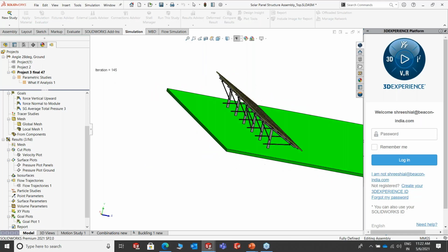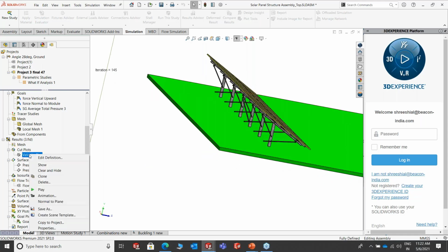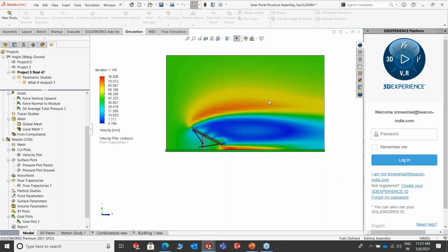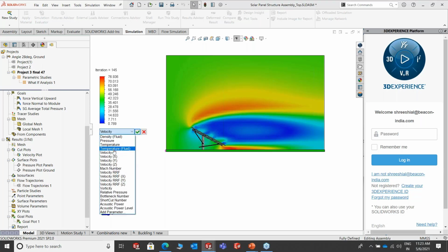Okay. Here again, coming to the meshing, the finite volume mesh is automatically created. There is no need for you to do manual meshing, and we have excellent post-processing functionalities for calculating various parameters related to fluid dynamics and thermodynamics. Here I have plotted the velocity distribution. You can just see how the velocity is varying when the wind is blowing from this direction in a positive Y direction. Not only velocity but also other parameters, as I said, the pressure.